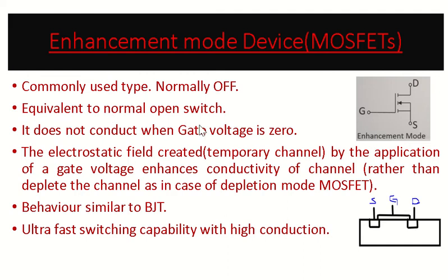It is equivalent to a normally open switch, like whatever switch we use in our day-to-day life. It's a kind of open switch, and an open switch means it's normally off. Unless and until we press the switch, it won't be on. Normally it will be off, but as and when we trigger or switch it on, it becomes on or enters the on state. So it does not conduct when gate voltage is zero. Now we will try to understand this in a very detailed way.